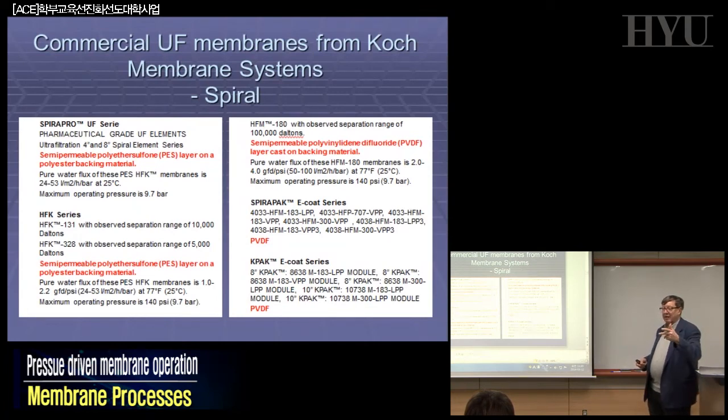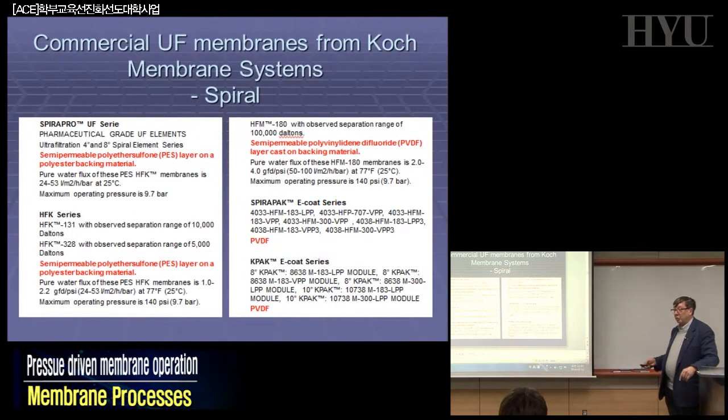The lifetime, instead of 3 months, is now about 1 year. And you reuse continuously. And the quality of this painting, when it goes back after cleaning and after ultrafiltration, is better than the initial one, because the membrane is doing a better job than the producer. So you can reuse and reuse and reuse most of your painting just in the bath. In the meantime, what you discharge is clean water, not colored water. And that is 100%. If you go to China, India, Europe, etc., an electrocoating ultrafiltration plant is always installed. And some of these membranes are doing the job.